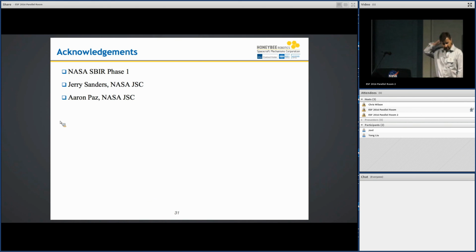So if you drill in icy soil, let's say at 60 Kelvin or 80 Kelvin, and you don't raise the temperature above, say, 100 Kelvin, you have no problem. But once you remove it and your drill sits in front of the sun and heats up a little bit, that's when the problem happens. The sublimation becomes exponential. So I'm not worried about what happens during the drilling, but what happens during the transfer. Thank you very much.